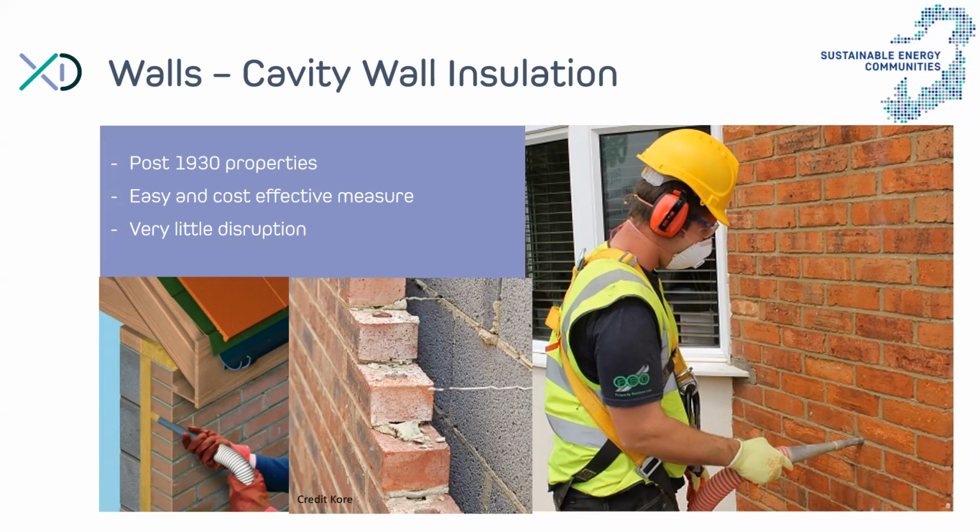Which means that in most cases, actually, there is a gap within that cavity. Either there's no insulation and you can pump that cavity entirely, or there may be a layer, but there's still a gap of maybe a couple of inches that can be filled. So the measure there, which is called cavity wall insulation, is to drill a hole at key locations on the wall and then pump